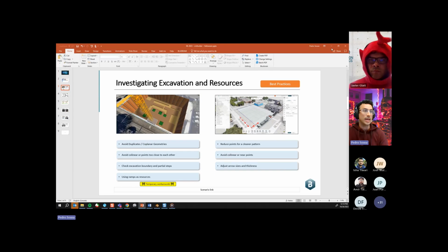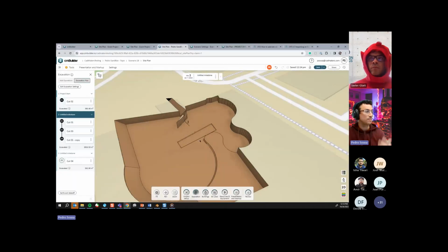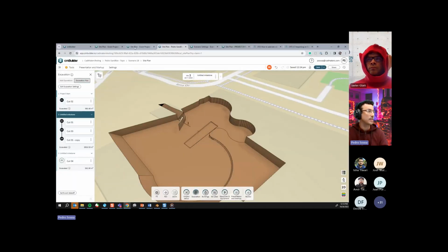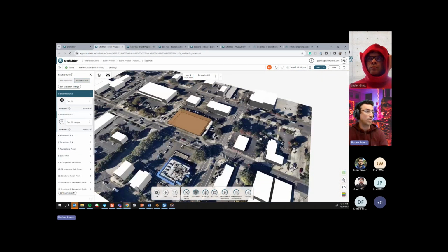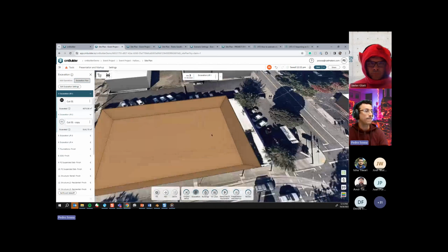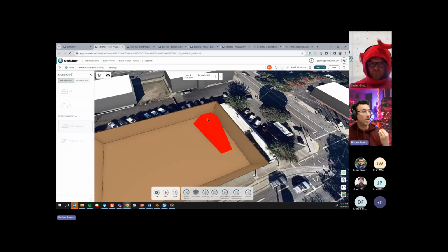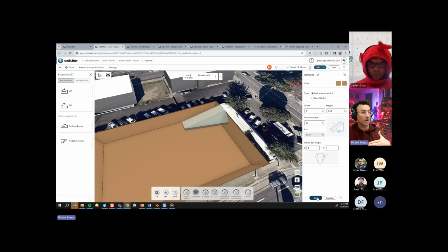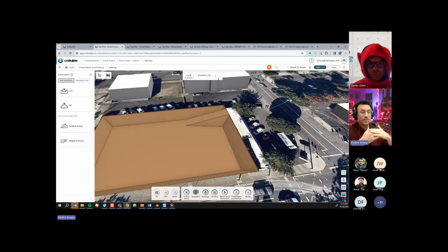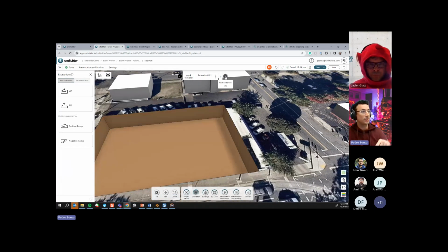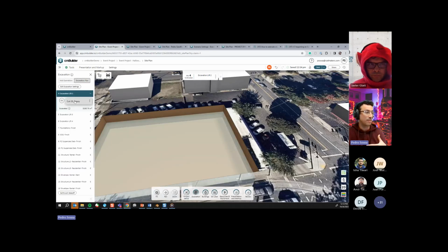Cool. And sometimes you are going to be working with ramps and things like that, and you want to create more and more ramps. And a ramp is also a Boolean operation. So if I add a ramp over here on my lift 1, and then I want that ramp to be on my lift 2, on my second stage, because I created a cut on the second stage that overlaps with the ramp, if I go to the second stage, that ramp is gone, right? Because my second cut is removing the ramp.